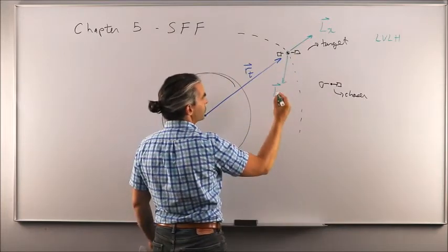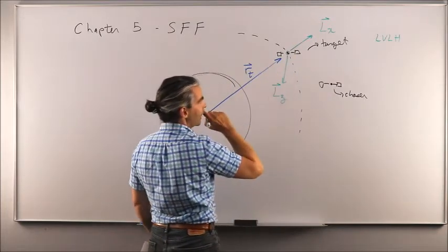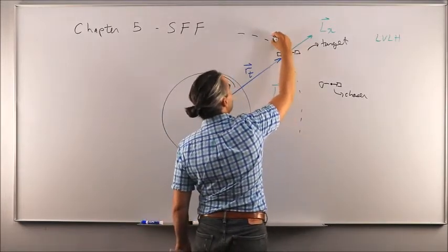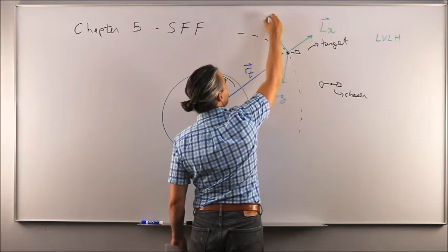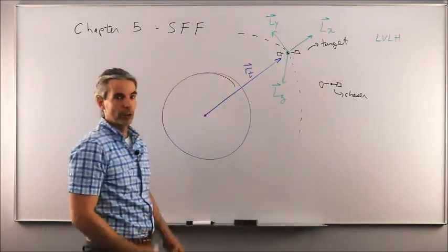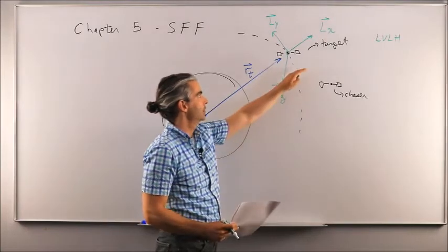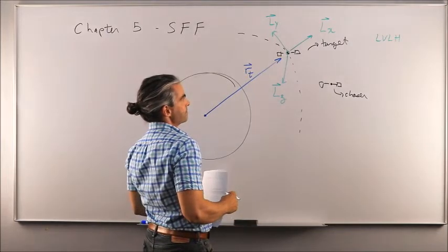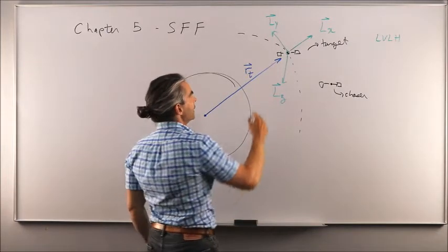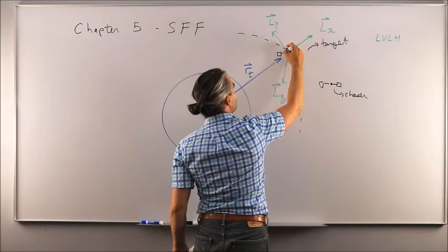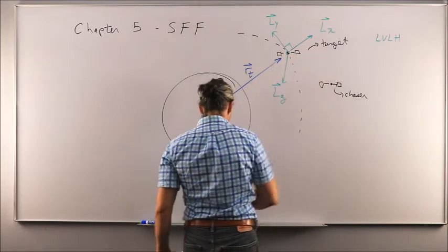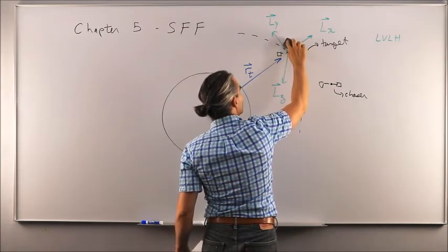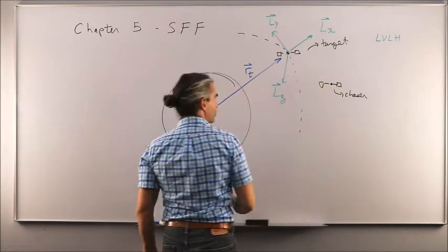And then, as per usual, the LY unit direction will be obtained by the cross product of LZ with LX, and would be something like this. Now, along a perfectly circular orbit, so in other words, if you assume that the target is following a circular orbit, then LX and LY would be perpendicular at all time, but that's only valid for a purely circular orbit, which may not be the most generic case, okay?